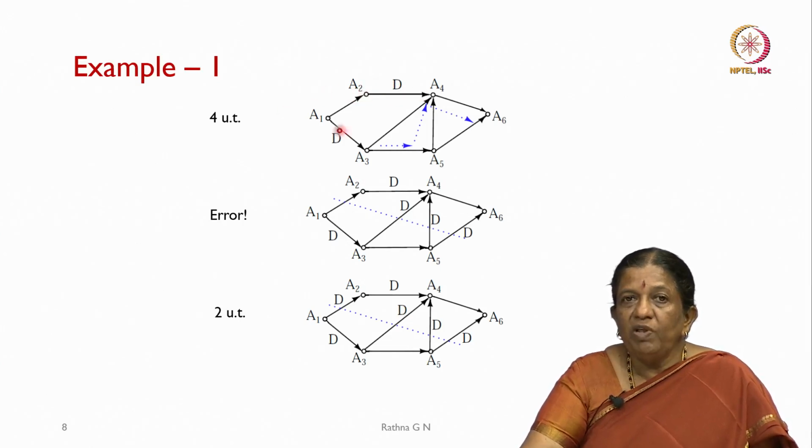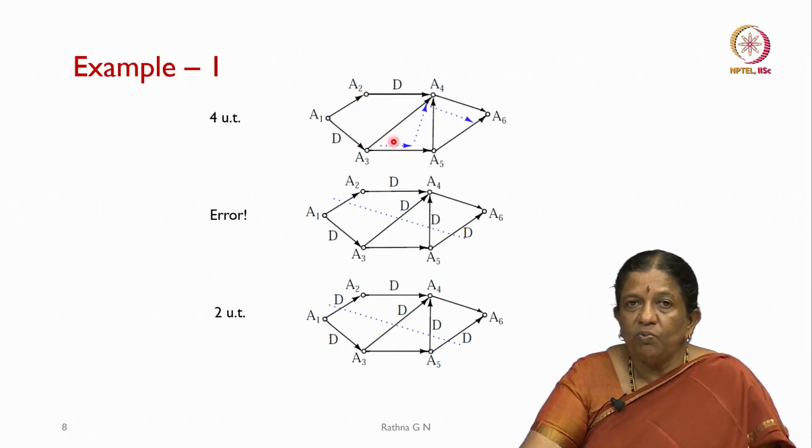What we have to see in this graph is the longest delay, which we call the critical path. Since there is a delay, we will assume that the data goes into a register, which holds the data, and then in the next clock cycle it goes into this point.